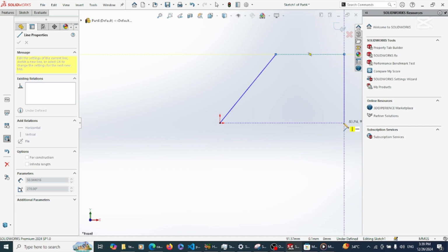Now this yellow box you are seeing, anytime you see these yellow lines, this yellow line I'm pointing to that turns blue, all these yellow lines are showing you the sketch relations that will be added by the time I click on this point. And this yellow one is showing you the possible relations.